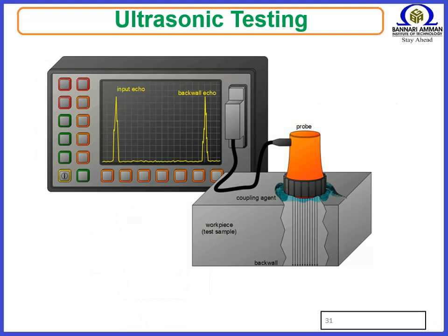Ultrasonic testing, UT, uses high-frequency sound energy to conduct examinations and make measurements. Ultrasonic inspection can be used for flaw detection/evaluation, dimensional measurements, material characterization, and more. UT is based on the capture and quantification of either the reflected waves, pulse echo, or the transmitted waves. Each of the two types is used in certain applications. Generally the pulse echo system is more useful.